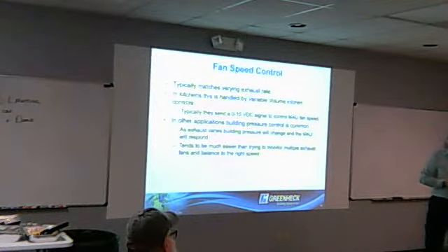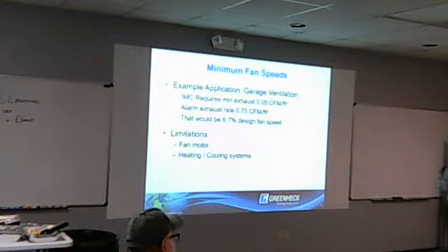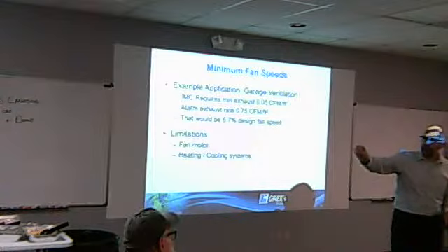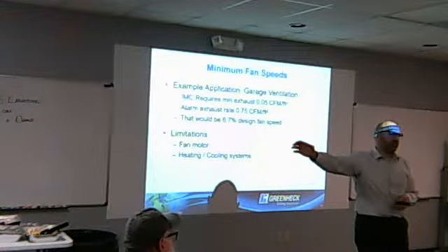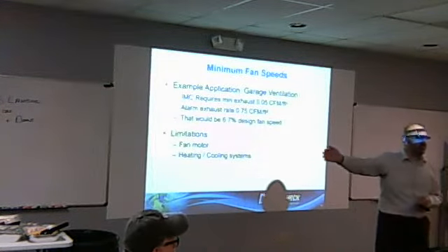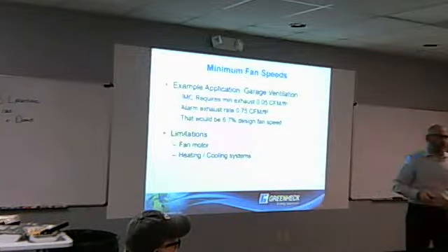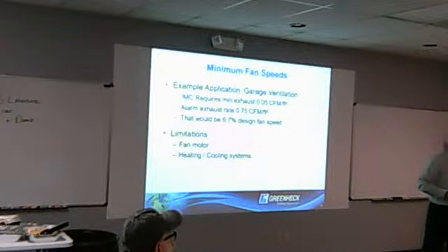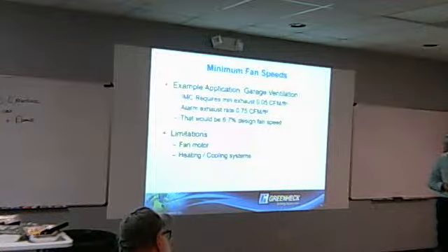Earlier, you mentioned you always keep a kitchen slightly negative. Why is that? Just to keep any odors in the kitchen as opposed to going somewhere else. If we oversupplied, we'd have those cooking odors going out into the hallway, into the restaurant. Exhausted into the bar area to get them to buy more food, like the old popcorn machine at the movies. Smells good, right? Yeah, so it depends on what they're cooking.